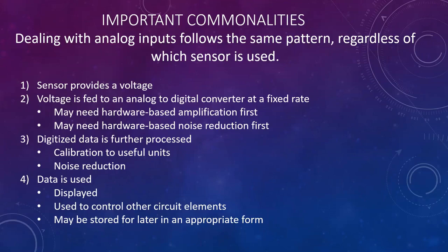A lot of these signals can be sensed very quickly, but for the equipment taking in that information, there's no such thing as continuous data in a computer. It's all samples. It's all sampling, I should say. To slow that process down a little bit, it's more like the computer is saying, what is the sensor value now? And then waiting, getting a response, storing that, and then saying, okay, what is the sensor value now? And it samples the real world that way. And it can do that very fast, but there's no such thing as a continuous signal. It's all discrete. It's all sample by sample.